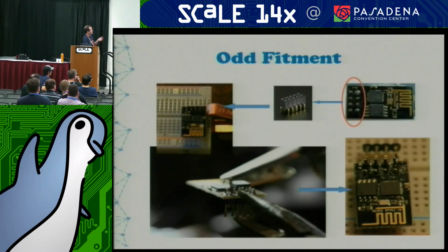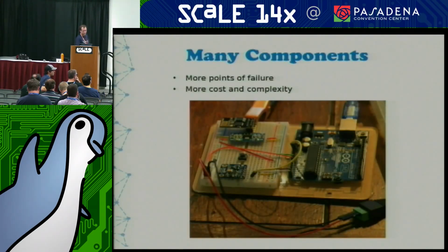So then you can, somebody did this, you can heat up a pin and then pull it up and then solder a kind of L-shaped right angle set of pins to it, and now you can bridge this gap. It's a really hokey fix, but it works well, and it seems to be reliable. But that's kind of silly, right? You have to do this for everyone, and it's just not a clean, efficient approach to it.